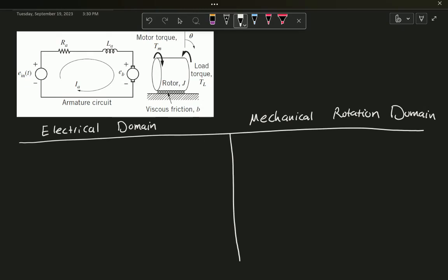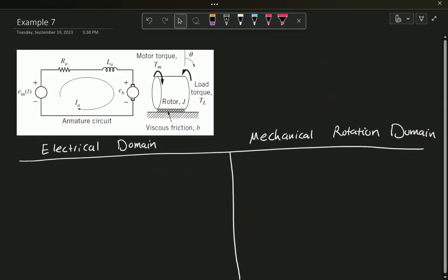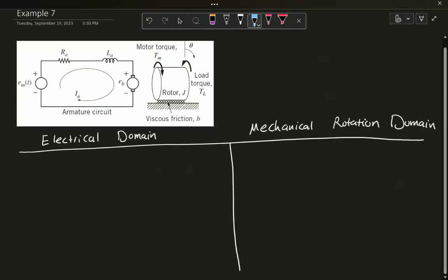And at the very end, I'm going to use the equation for the gyrator to connect one energy domain to the other side. What was the equation for the gyrator? If you guys remember, we had torque of the motor equals Km multiplied by I, which I'm going to show with I of armature, and also we had back electromotive voltage equals KB theta dot.